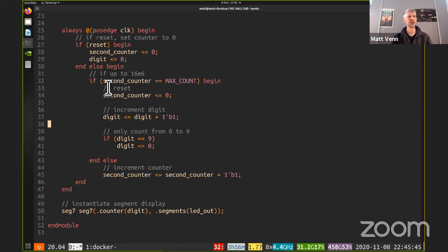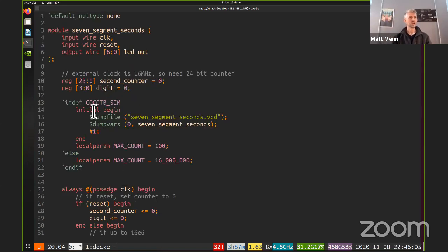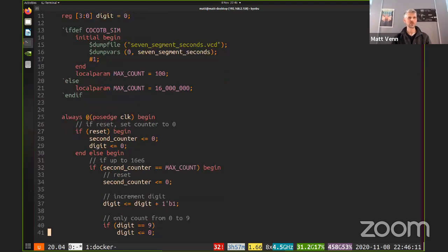And when I say something like this, I'm saying build a set of combinatorial logic that connects to each of the flip-flops in second counter that can do a complicated add or XOR, whatever, until it gets to a single signal that goes high if it gets to 16 million and is low at all other times. And when I say register, what I'm asking for is a whole load of flip-flops all joined together in a way that lets me use them as a block of memory.